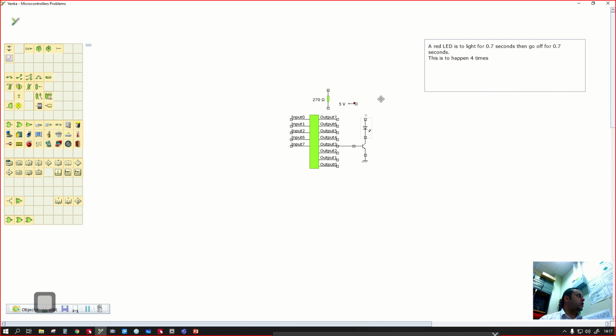And then I'm going to put a resistor in series with it, because we always use a resistor in series with a light emitting diode. Light emitting diodes are so low resistance that if we were allowed to put any more than maybe 1 or 2 volts across it, the light emitting diode would just get destroyed. So that's me got the technology of my system set up. I've got an NPN bipolar junction transistor in there as a transducer driver, to make sure that the LED gets just as much energy as it needs to do its job.